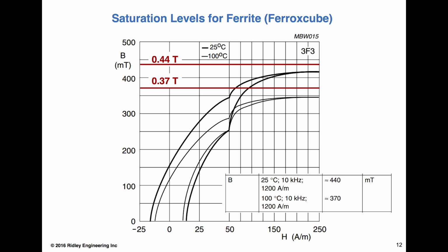But the performance things that are going on is, if you have a multiple-layer PC board and you want to turn it into an inductor, because there's some free space on there, and you say, okay, I've got 20 layers on there, you have to think about, well, how is a 20-layer PC board made? It's fabricated by making lots of 2-layer PC boards, pressing them all together, and then getting solder to fill in between all the layers.